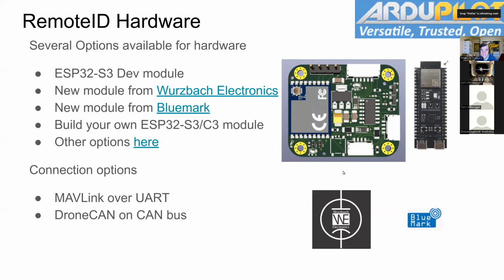Sure. Right now I'm planning to do an ESP32 module in the immediate term, and then as I can find and secure supply of the Nordic devices, I will introduce a Nordic-based device, and we'll go from there. I have selected one. It's an NRF52840, the most probable solution. There are some newer items worth considering, but most of the modules I've seen that are going to meet requirements are based on the NRF52840.